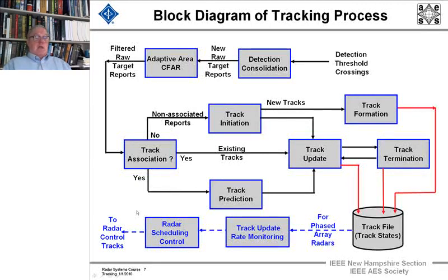Say we have a target in track, and we've designed it as a missile tracking radar. There we're going to want to get a nice quick update. You want to get an update, might be every 1/10 of a second. So we'll schedule the radar, if it has a very fast speed, as a missile might, to go every 1/10 of a second, bang away.